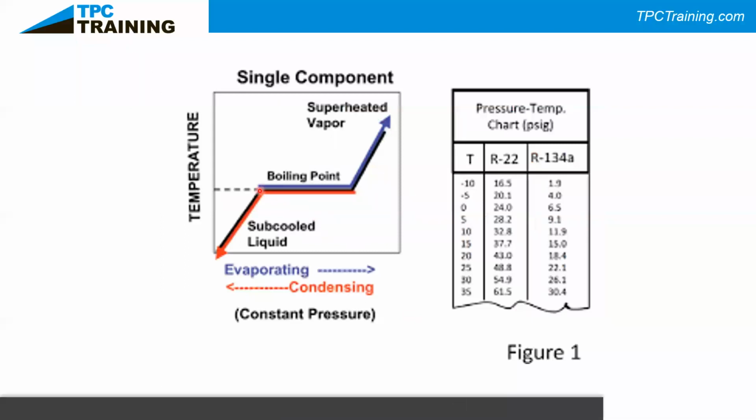What we're looking at is this. We take our saturation temperature, and once we get past evaporating, changing from a liquid to a vapor and then rising in temperature, once it changes to 100% vapor, how much extra heat are we adding to make sure we're protecting the compressor from getting liquid back on it? Then there's the subcooling we're doing in the condenser. We take our pressure on our red gauge, convert it to a temperature, and then compare it to the liquid line; the difference is our subcooling. So that's why this PT chart is so important.